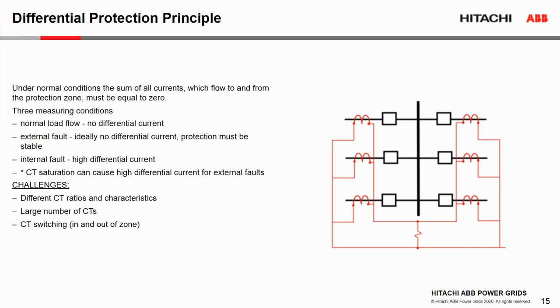And CT switching in and out of zone, we mentioned this many times prior: based on the disconnect status, the CT needs to be switched in and out of different protection zones.